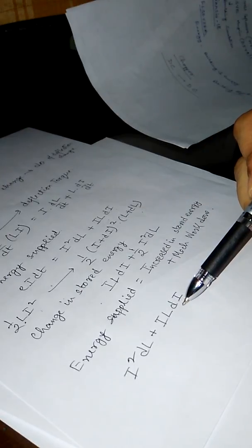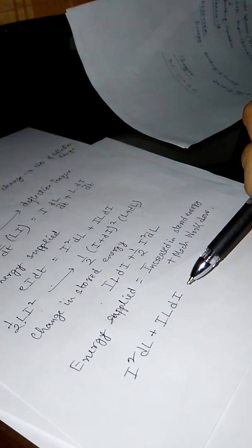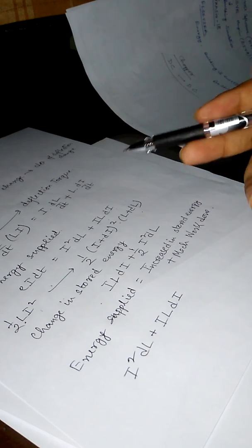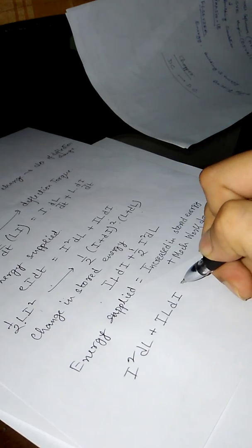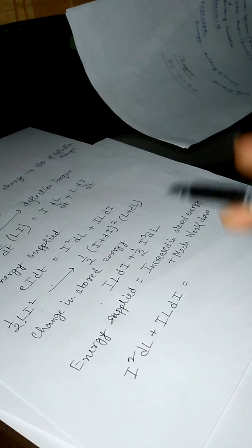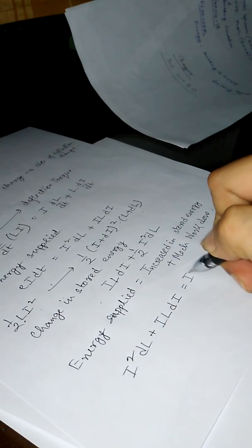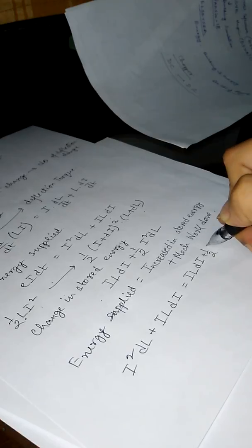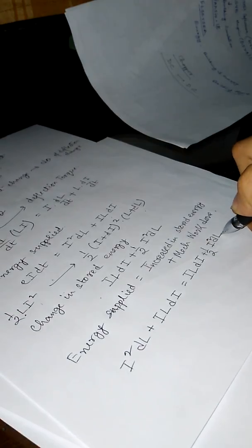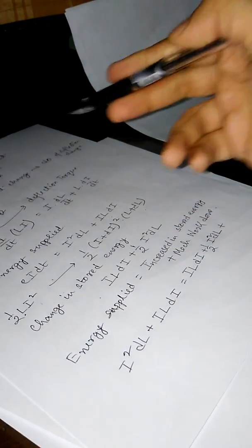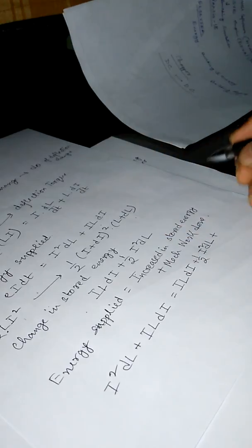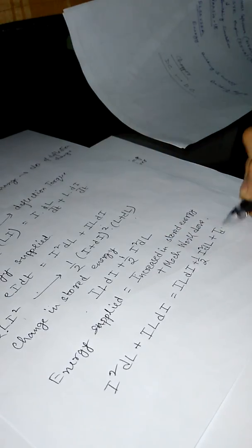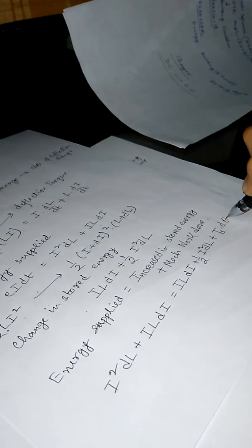This is the amount of energy supplied, that is equal to the increase in stored energy, that is IL dI plus half I square dL, plus the mechanical work done, that is Td into d theta.